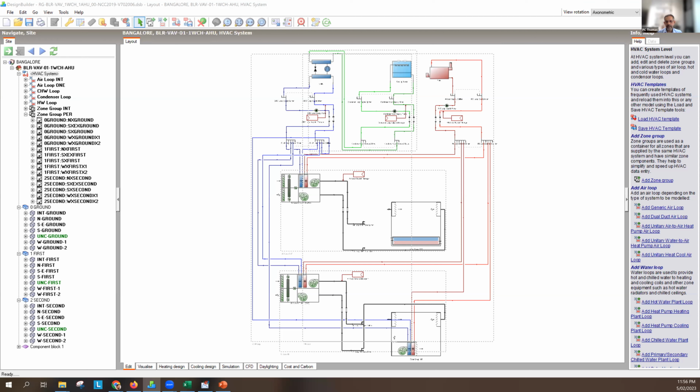In contrast, when you use any sort of split system or direct expansion system, VRFs, split systems, whatever, then you're not pumping around water, you're pumping around refrigerant. Okay. What is the implication of that? If your strategy is to reduce greenhouse gas emissions from your project, then you need to start thinking about direct emissions from leakage of refrigerants. Why is that important?